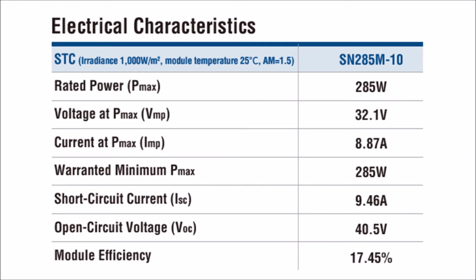Let's get back to the basics with module specification sheets. The module power rating is how many watts of power the panel will output under certain lab test conditions. This information can be used for pencil and paper design, but nowadays most design decisions are guided by computer design software. This solar panel is an older model, and so it has slightly lower wattage than most solar being installed today. Most 60 cell solar modules today are around 350 watts, just under 10 amps and 40 volts.